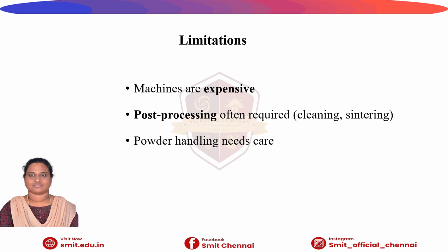The machines used in this process are expensive, which makes the initial investment high. After printing, the post-processing steps such as cleaning, sintering, or heat treatment are often required to achieve the desired strength and surface finish, which increases the time and cost.